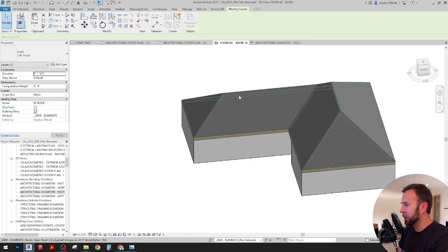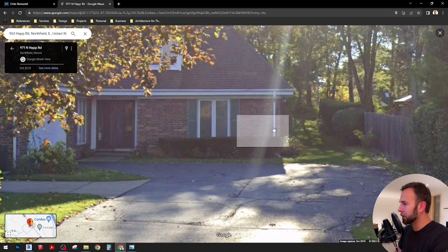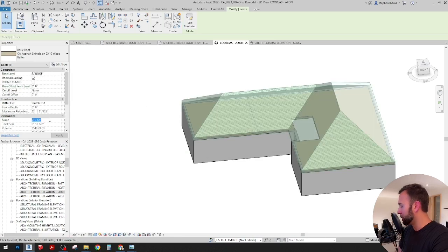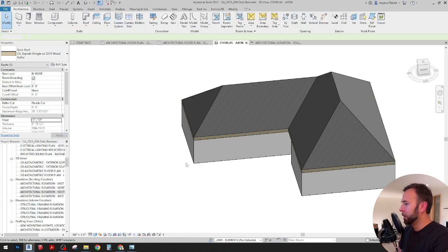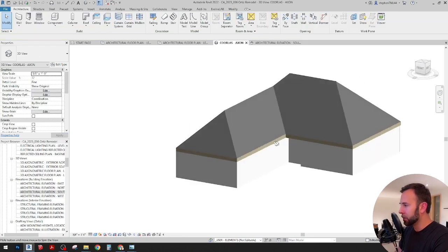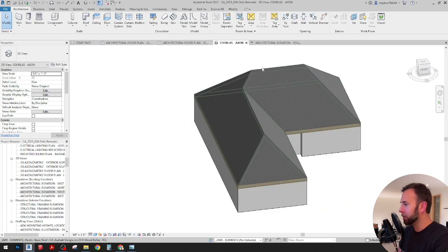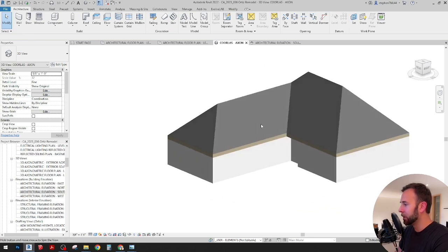I'll have to take a section slice through here and measure 16 feet up to see how close we are with the roof line. Just taking a second look at it, it definitely looks like it could even be over a 12 by 12 pitch roof. So let's just start with the 12 by 12, and that looks a little closer, and looks like Revit did it right with the hip kind of extending up there a little bit.